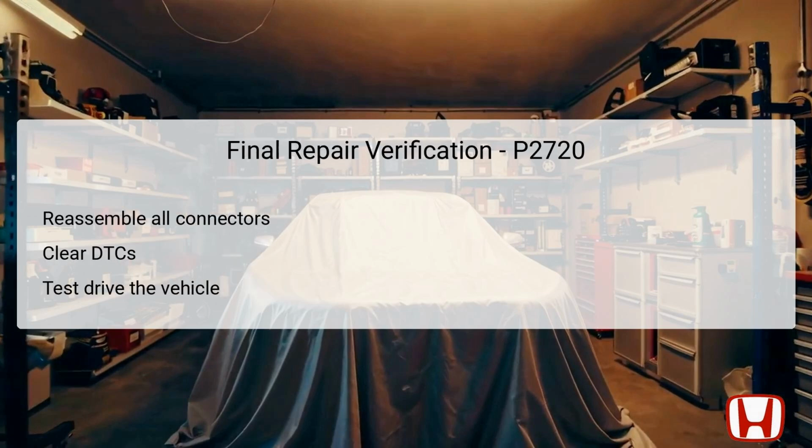After completing all necessary repairs and replacements following the troubleshooting steps for DTC P2720, it's essential to perform final repair verification. Begin by reassembling all connectors and ensuring that each is properly seated and secured. Next, use the HDS to clear any stored DTCs, resetting the vehicle's computer systems.